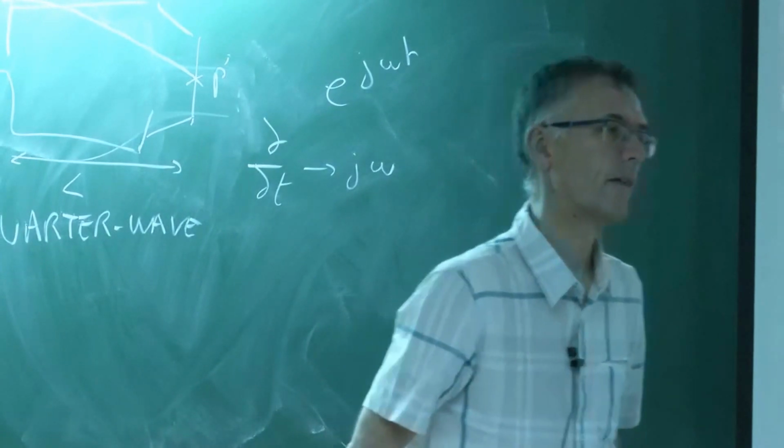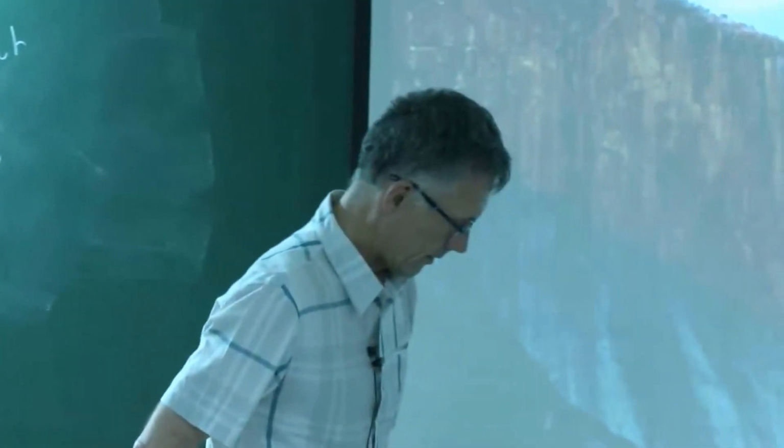So, we are trying to simulate instability using LES. Like Ralph told, here gets dissipated, which is not there in LES. Yeah. So, what other things should I be careful about when I'm doing simulation of thermoacoustic instability in LES? Well, that's exactly what we discussed yesterday. I think you need a code which does not dissipate energy. A code which can convect vortices correctly. Yeah. Otherwise, you won't have anything.